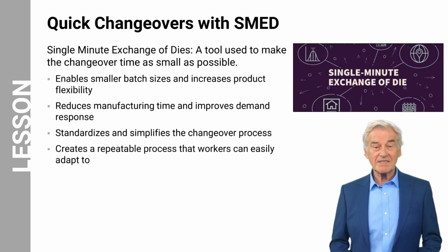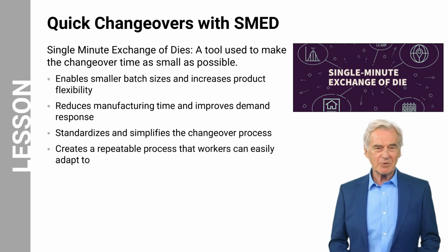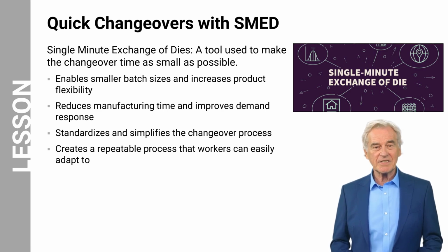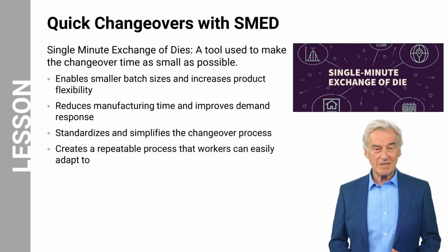SMED, or single-minute exchange of dies, is a method used to reduce changeover times so that each setup or changeover is reduced to a single-digit time. Single digit or single minute means less than 10 minutes, but the goal of SMED is to make the time as small as possible. SMED implementation makes smaller batch sizes practical, increases product flexibility, reduces manufacturing time, improves response time to demand, and standardizes the changeover routine. The result of SMED is a changeover process that is standardized, repeatable, and one that workers can easily adjust to.